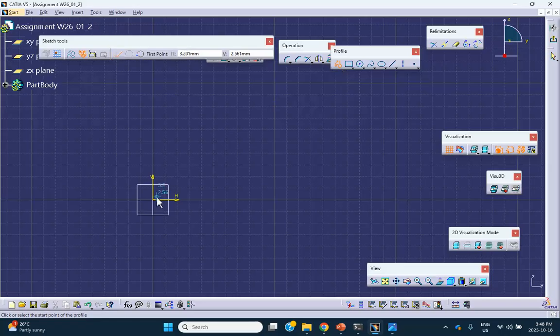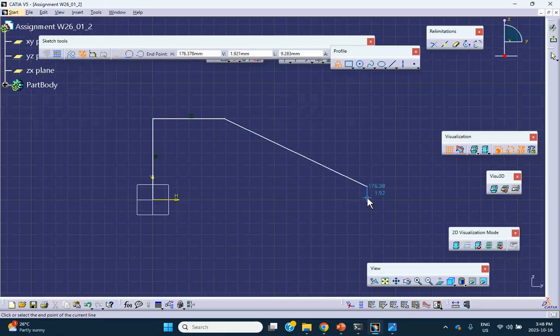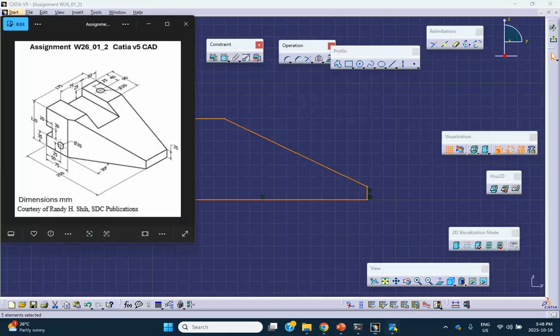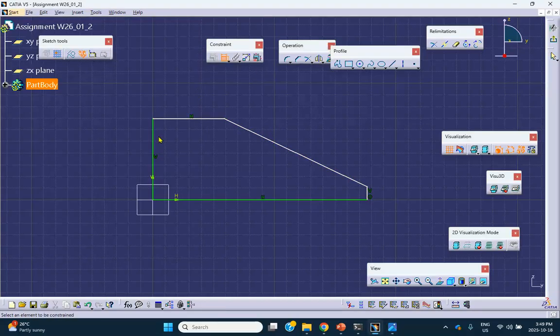So on this plane, I will sketch that trapezoid that I was talking about. It looks something like this. The dimensions we have to look back and make sure they're right. So it goes like this. This is the back side that you can see. Let's put some dimensions here. The height is 120 on the back, and the length is 250. So this is 120.